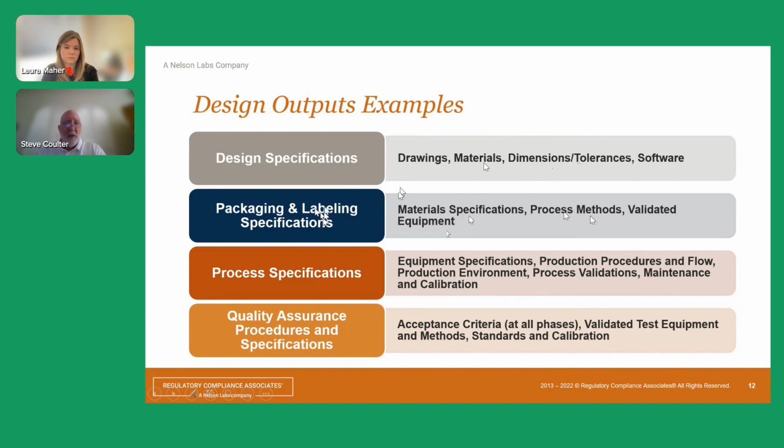What adhesive is on the labels? What's the paper that the labels are on? And then the validation of the equipment to make sure that the equipment is capable. If you say, I'm going to put a label on a pre-filled syringe, is your equipment capable of putting on the same place each time? Things like that. So these are things you work out during the design process.